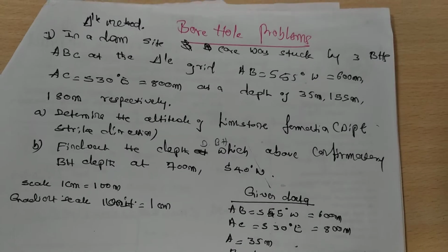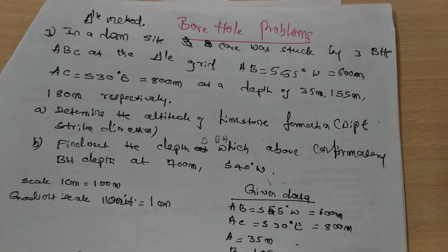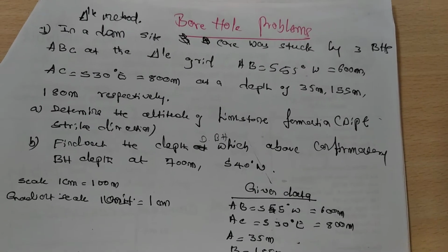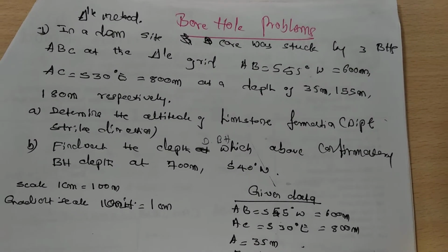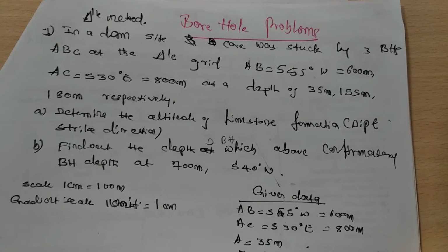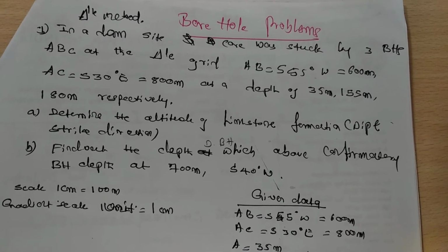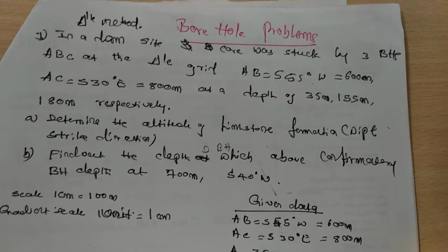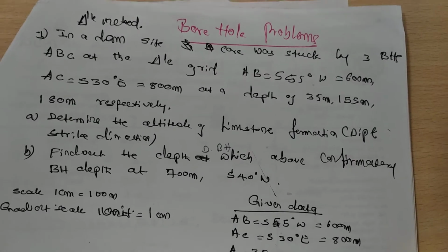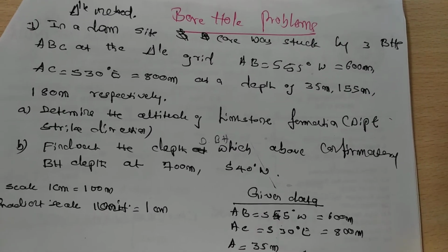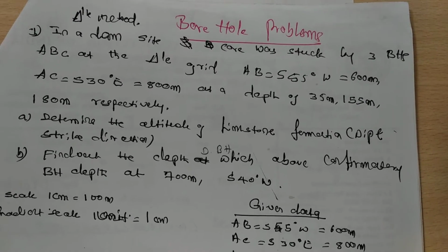For mineral exploration, generally we drill boreholes for a minimum of 300 to a maximum of 800 meters, or even more than 800 meters. For oil and gas, we may go for kilometers, maybe 3 or 4 kilometers down below the earth, to understand the subsurface geology, geological structures, different rock types, behavior of the rocks, and dip and strike of the rocks. And from a geotechnical point of view, whether it's hard rock, soft rock, or unconformities and geological structures, these boreholes give us a very good idea of the subsurface strata.